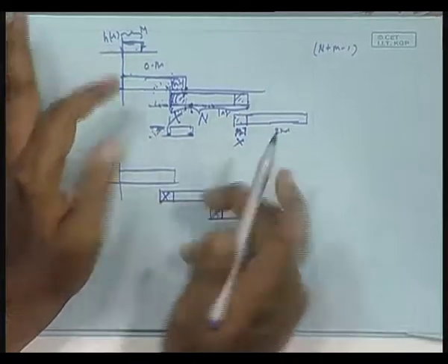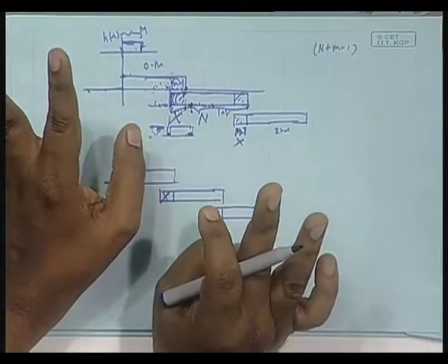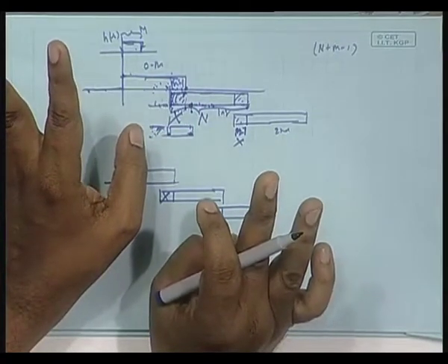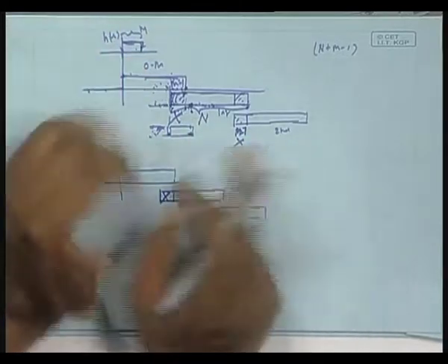Okay, so simply linear convolution with the two blocks can be acceptable in the final result. Second, that figure m minus 1, I do not care either way. This is called the overlap and save technique. You see, I just live happily with n point DFT only, not n plus m minus 1. These are the DSP tricks.